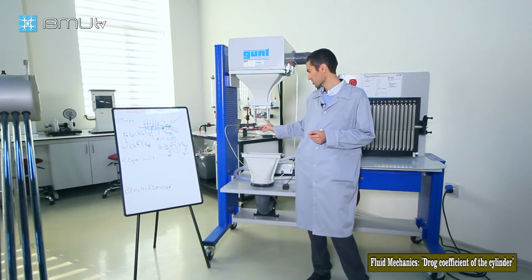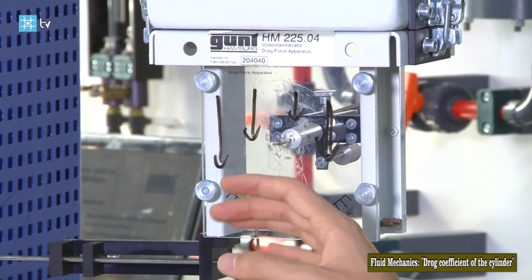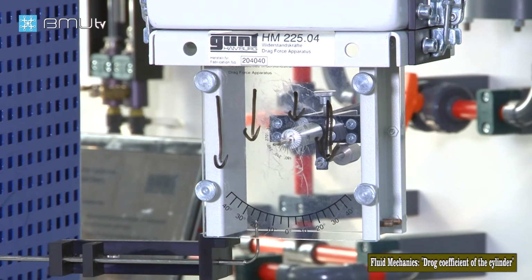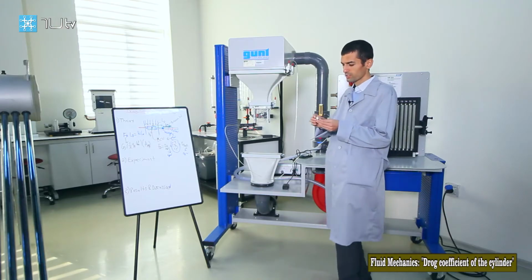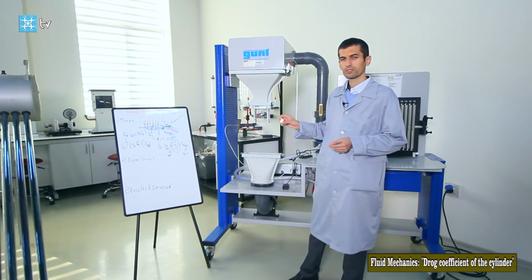I will put the pitot tube at a distance that is not disturbed by the body or by the presence of this measuring section. Because the walls, the solid boundary, also affect the flow due to the no-slip condition, as does the presence of the cylindrical body. Therefore, I will put it at some distance that is not affected by any of it. Okay. So I will start the experiment now. As I said, I will set the flow to the maximum speed, and then I will try to balance it with this weight here, which is 40 grams.